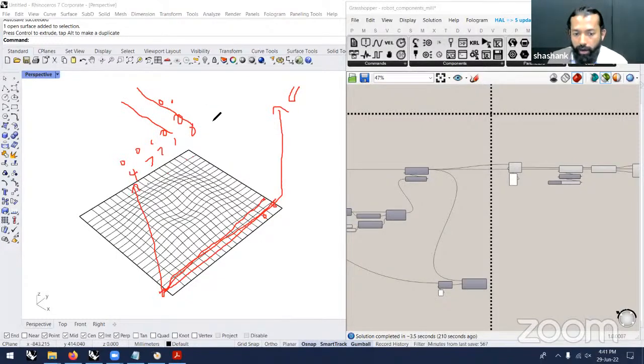So once the robot moves through all this set of points, it will again try to restart the list. Even after it's exiting, it will go to the second row, which is down the line out here, and then it will continue across all these points, then clear these points and start from the row again from the beginning. This is a slightly inefficient way of milling. What would be nicer is if you were to go along one path, exit from it.